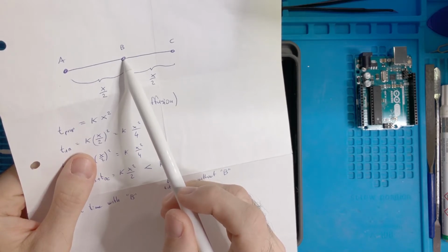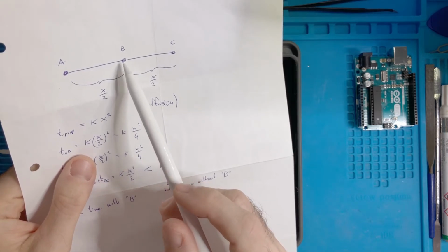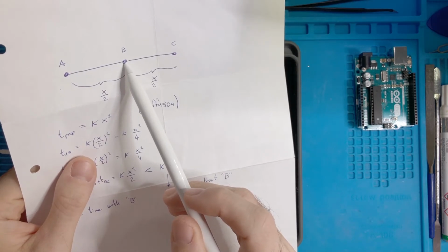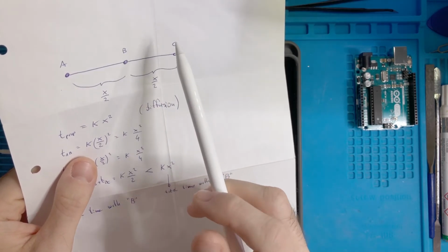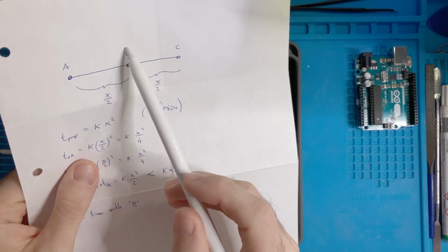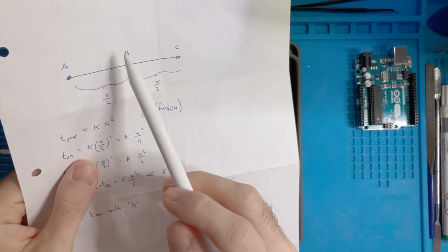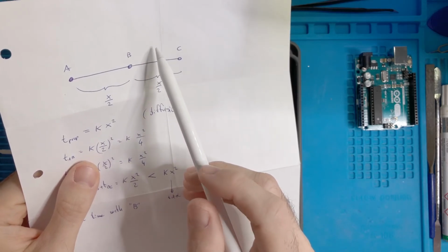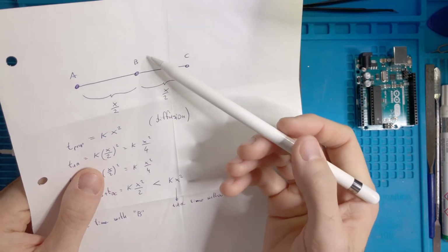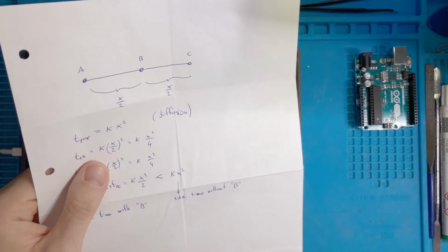Let's say a repeater, an amplifier, so instead of going directly from A to C, we go from A to B, and then we have a repeater in B, and from B to C. For instance, a repeater for us can be two NOT gates, one after the other one. We know that NOT NOT something is like you did nothing, but the signal is regenerated because inside the gates there are amplifiers and whatever.